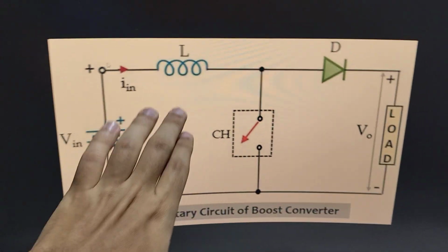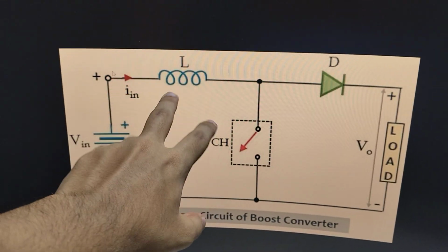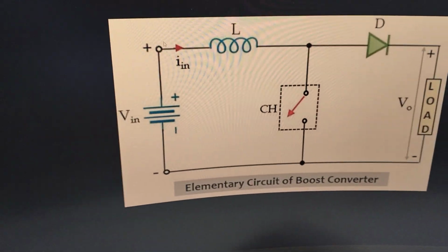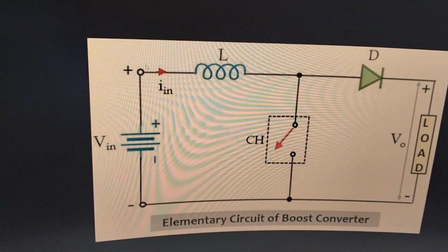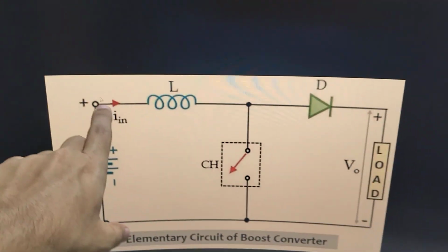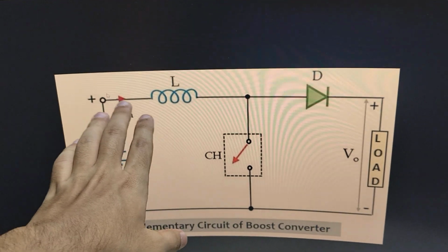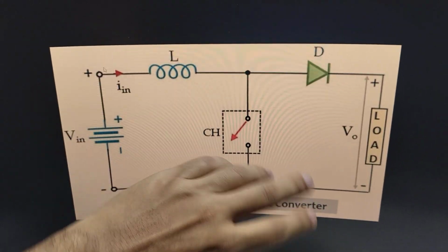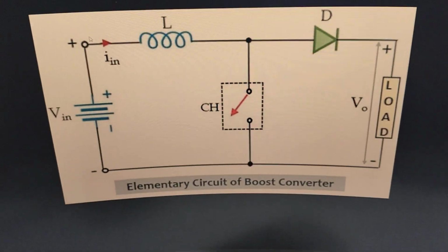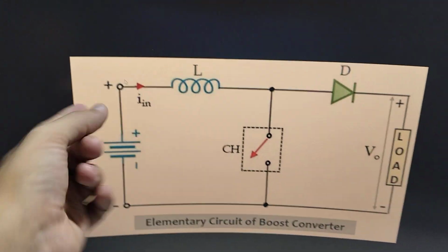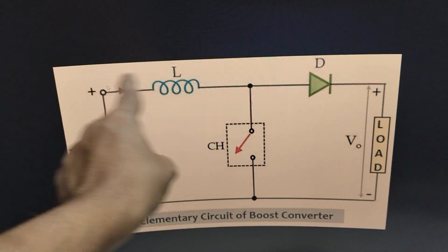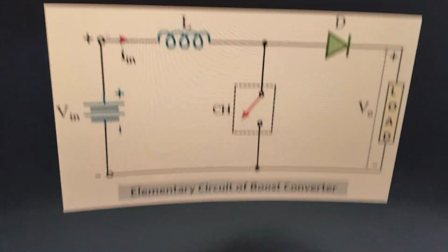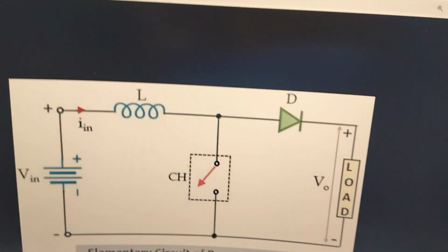That's very dangerous, because the inductor, after all, reacts to changes in current, L di/dt, the voltage across an inductor. So in steady state, it can actually start acting like a low value resistor, basically a short circuit. Like in a DC circuit, if you use an inductor, it essentially acts as a short. In the same way, a very large current would flow through this and even destroy your entire circuit. So definitely you need to limit the duty in a boost converter.